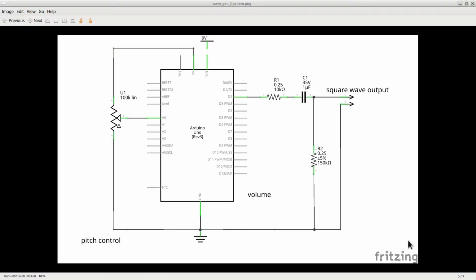Here is the schematic of the circuit to do that. Yes, it is the same schematic we used to generate the square wave with the tone function. The fact is that to generate a square wave using a wavetable, we only need 2 values in the table itself, and to represent 2 single values we just need a single digit. We don't need multiple digits like we would if we were generating a sine wave or a triangular wave. And so we will use the same circuit.